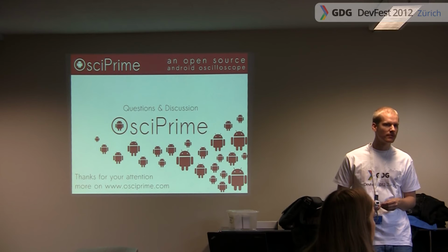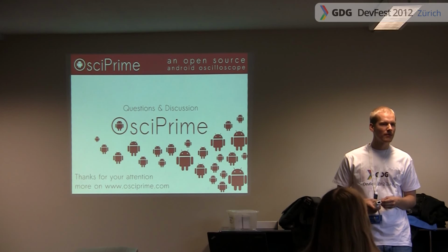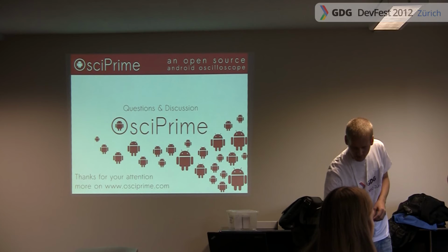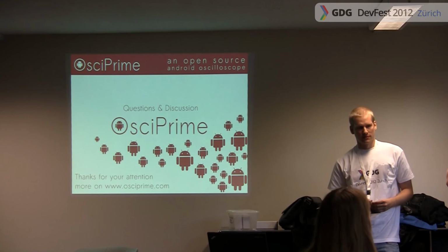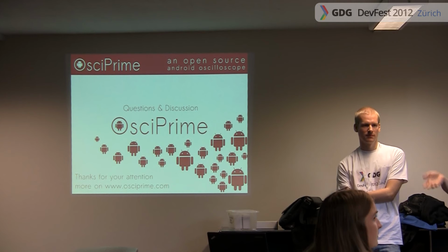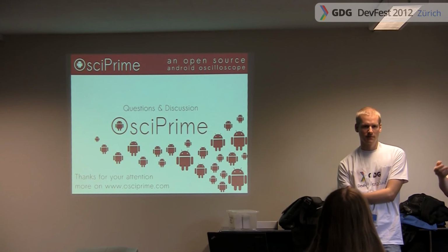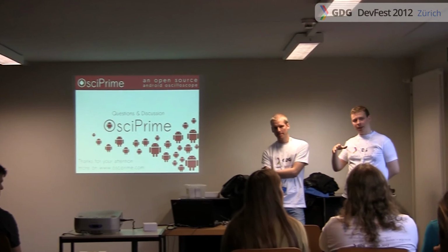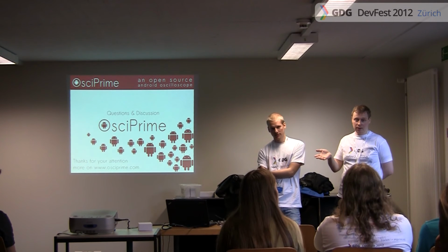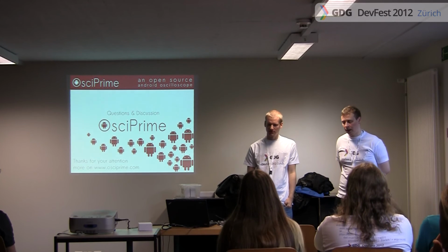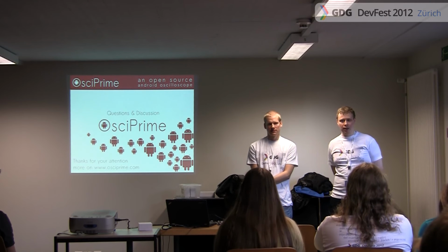What's the latency from when the signal is first received on the board to actually being displayed on the screen? Well, the FX2 microcontroller is hooked up directly to the CPLD, and we sample about 400,000 samples. This takes about 32 milliseconds, and with that we get a rate of about 30 frames per second on the screen, so we have a fluid display. So the latency is one buffer, about 32 milliseconds. But you can do this however you would like, since you only gather data. You can create your own libUSB software, which isn't that complicated, and then you can display smaller or bigger buffers, or you can even change the Android firmware. However, you need to adjust the time scales.